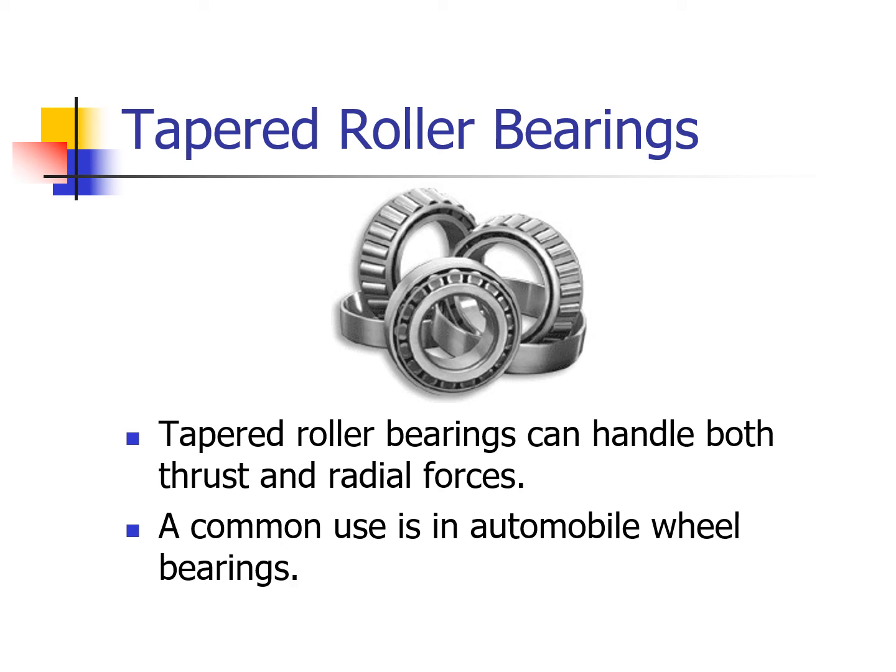A radial force is a force going outward, and a ball bearing and a straight roller bearing could both handle a radial force. But if I put a sideways load on that, which is called the thrust load, that bearing will actually fall apart. It'll just push through.